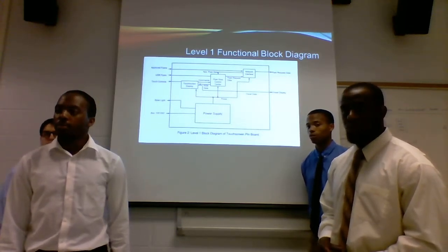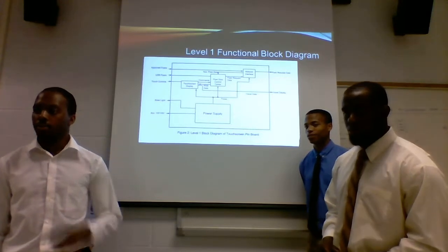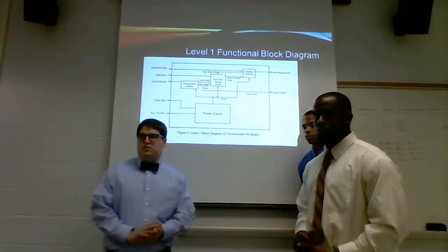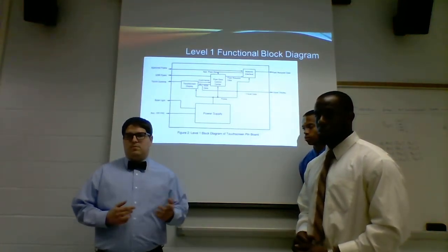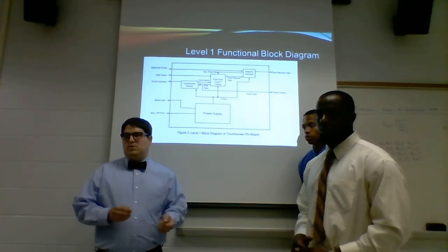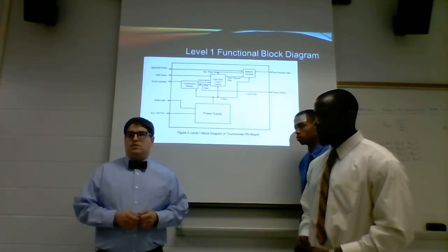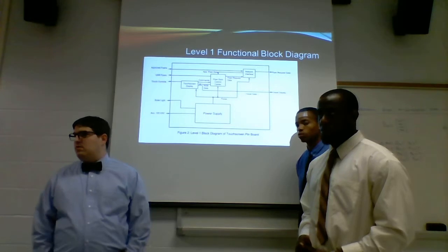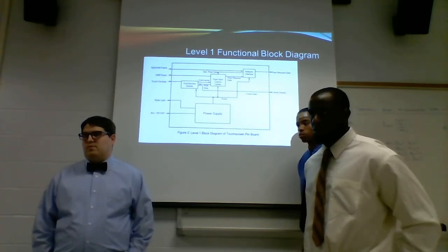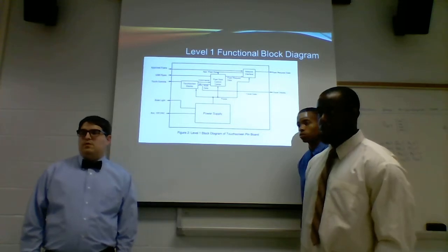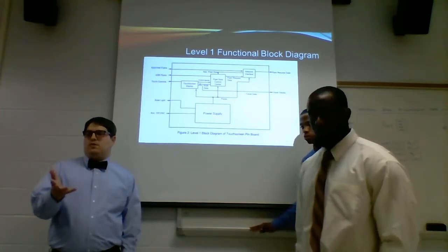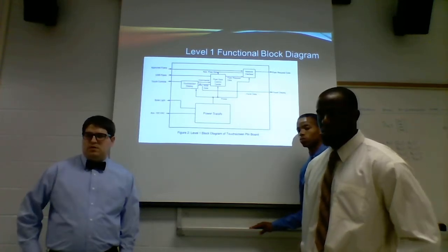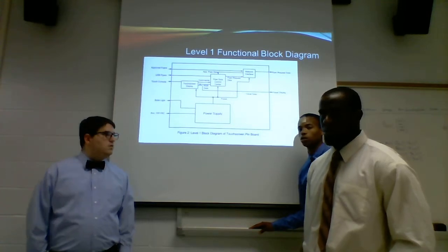I had another question about the solar panel. You're saying you disconnected the LED? Yes, there's an LED that was in parallel with the positive and negative lines. We took that out of the circuit, and it was apparently a big drain on the power. The LED was an indicator that the solar panel was receiving power. When it was producing power, the LED came on. It's just a simple LED and resistor in parallel with the circuit. It's not really necessary.